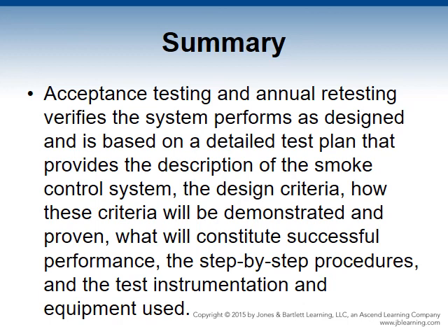Acceptance testing and annual retesting verifies the system performance as designed and is based on a detailed test plan that provides the description of the smoke control system, the design criteria, how these criteria will be demonstrated and proven, and what will constitute successful performance, the step-by-step procedures, and the test instrumentation and equipment used.